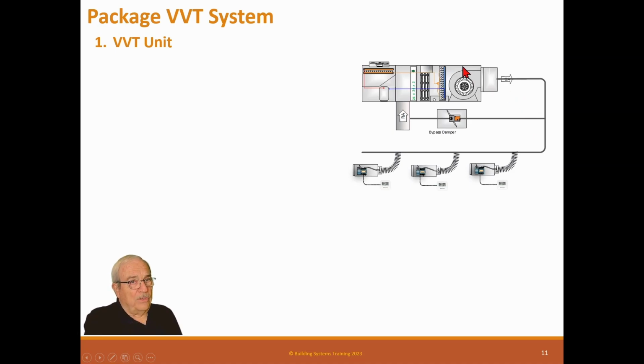The other problem was we didn't have good DDC controls. We were trying to do it with electronic controls, which are not DDC, totally different. So we had to do a whole bunch of Mickey Mouse stuff out here. We had to have zone controls, worrying about cooling and heating and being able to switch over, and it was very complicated to do electronic controls on this. It made it so a lot of systems just didn't work well. People couldn't deal with them, so they basically ended up ripping them out. But nowadays they do work, and they can work.